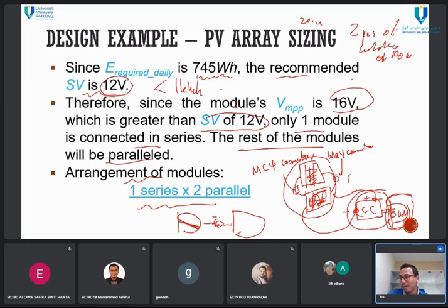I will release assignment today because we can't wait anymore, because drag untuk lab tu macam okay lah. Siapa yang tak dapat 3 kilowatt you can reduce it 1 kilowatt only lah. Okay, last discount 1 kilowatt only. It looks like there's some problem, and make sure again I state, make sure you have to produce first of all the IV curve for a single PV cell. You have to make sure that you get the IV curve, exactly what we have learned before in chapter 3, that curve. If you can't get that curve, means your system, your circuit is still not correct. You have to work on until okay.